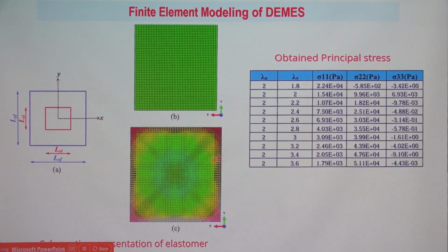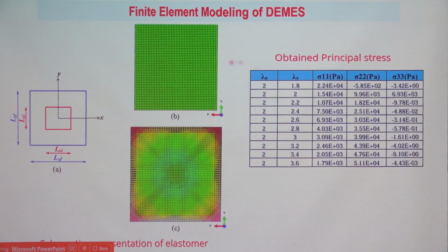Basically, initially this is your membrane, and when you give the displacement, as an example, we started with 1.25 pre-stretch. So we have given 0.125 here and 0.125 in this direction, and 0.125 here and 0.125 here. So ultimately what you are giving biaxially, the displacement will ultimately serve as a pre-stretching for the membrane.